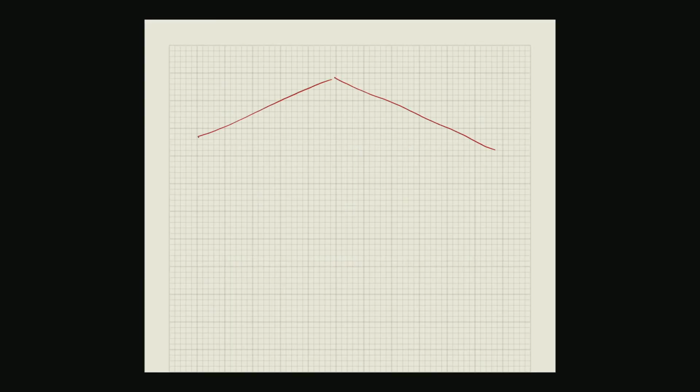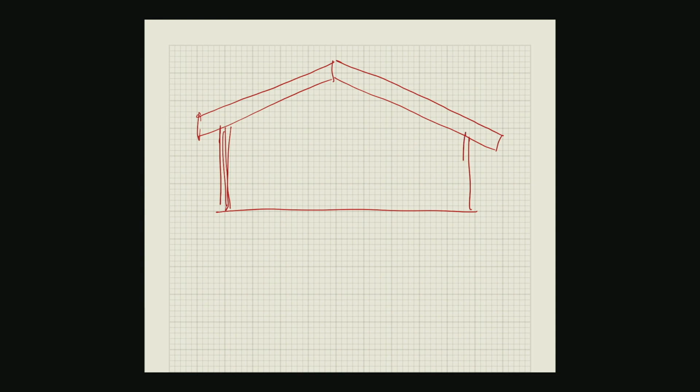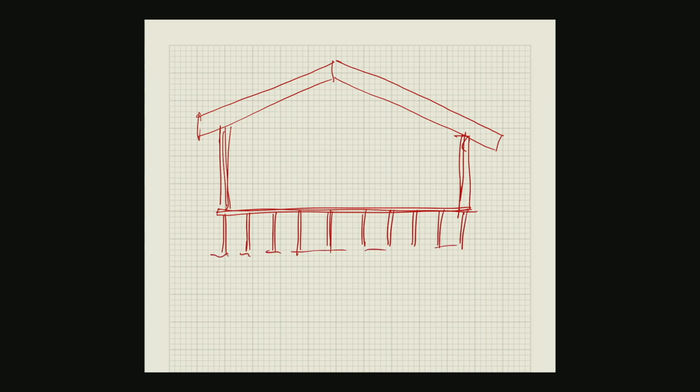Okay, so the roof truss like this. This is a factory. In a factory or warehouse, it's going to be pretty much like this. You have the floor slab. In Thailand, the soil is very soft, so you have a bunch of piling works to make sure that you do not have very bad settlements in the factory floor slab.